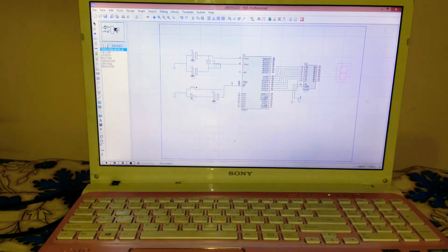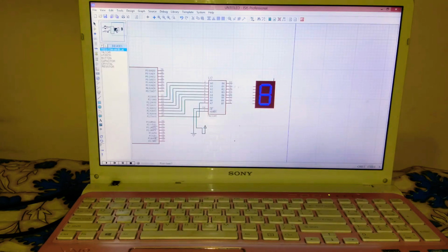So here we go. We're just switching it around here. Yeah, that will be perfect, so that we can connect the pins very easily. So connect pins 11 to 18 to these 7 pins of the 7-segment display. Alright, so start connecting this. I will start from the bottom. So it's been connected here. While connecting, just be sure you connect it properly, because sometimes we connect in a hurry. So basically we miss some connections and the circuit doesn't work.